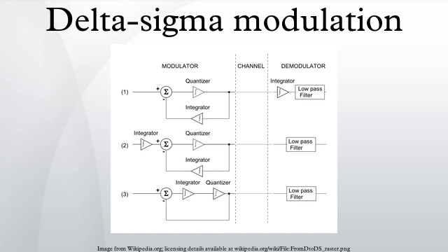It is the pulse stream which is transmitted for delta sigma modulation, but the pulses are counted to form sigma in the case of analog to digital conversion. Analysis. Shown below, the block diagram illustrated in Fig. 1, are waveforms at points designated by numbers 1 to 5 for an input of 0.2 volts on the left and 0.4 volts on the right.